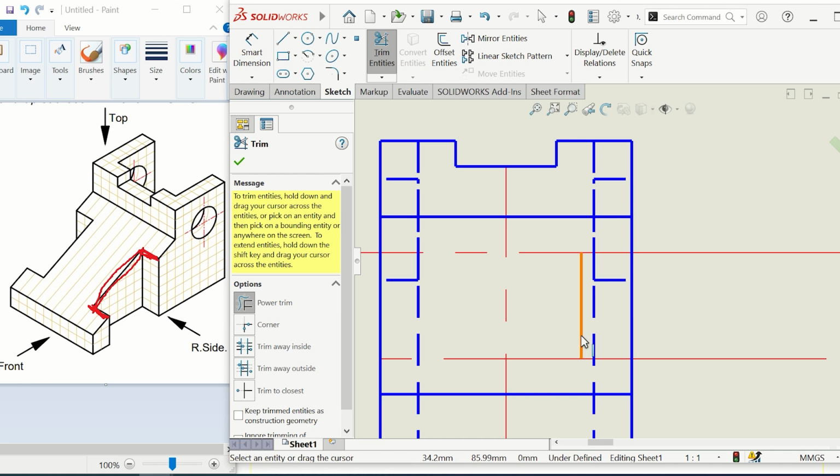Okay, now this line here is actually this line. Let me draw it here. It is this line. And its correct position on the front view, and its correct size, not the real size, the correct size that it appears in the front, which is a distorted size. The size of this line is shorter than what the real line is. It's the projection to the front.